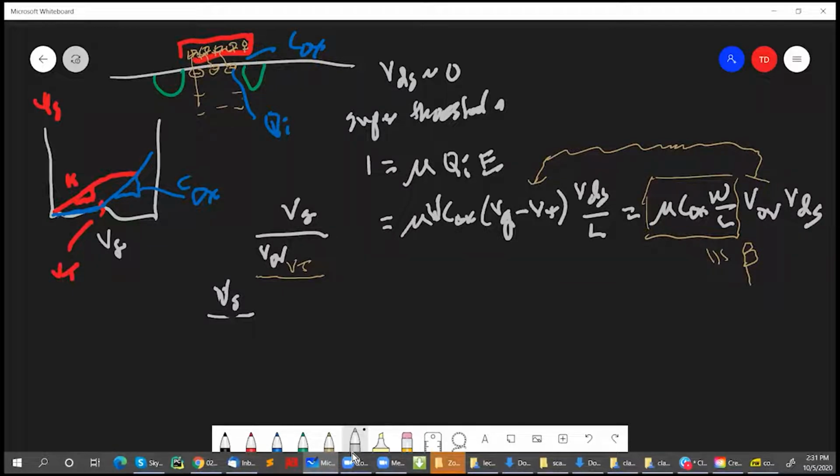Okay. So now you have a drain voltage. At what drain voltage do I need to put the drain so that the drain voltage is just at the threshold voltage? So let's copy this overdrive voltage over here. And if we put that here, there'll be some overdrive voltage. And let's just say the source is ground here. If this voltage is the overdrive, the drain voltage is exactly the overdrive, then you could see that the drain end of the channel will just be inverted by the threshold voltage.